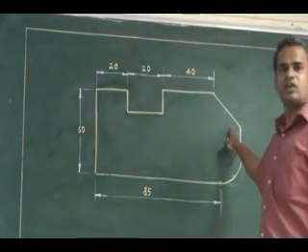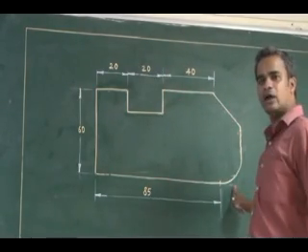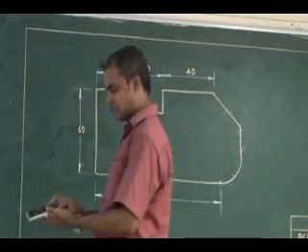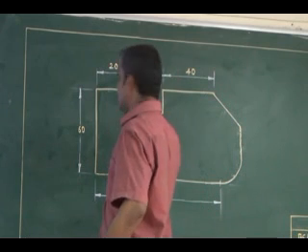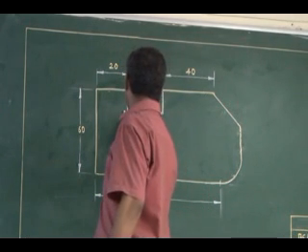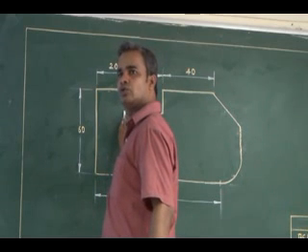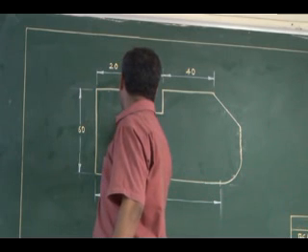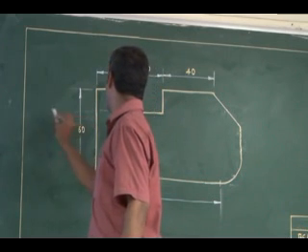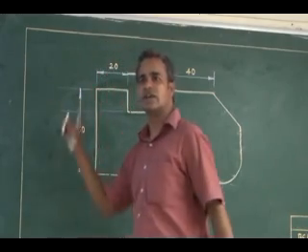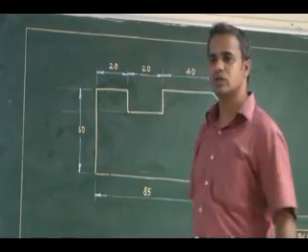Now this is a 45-degree inclined line. This is an angular dimension I have to show. Now you see here I have a dimension entity, its height, 10 mm. I have to show it anyhow in my drawing. So this 10 mm, if I extend an extension line like this, what will happen? I have to show this 10 mm outside. Is it right? You see the principles.